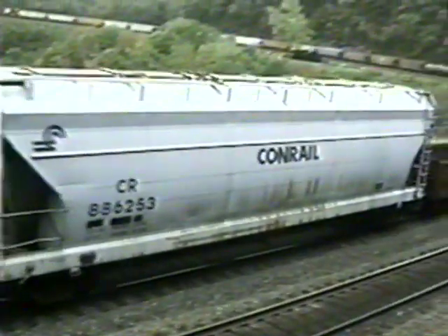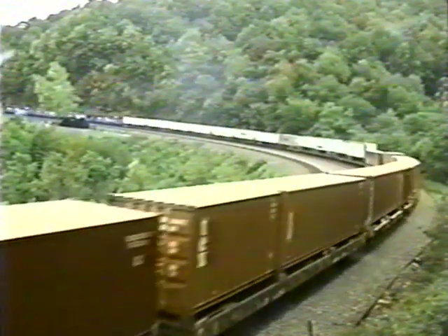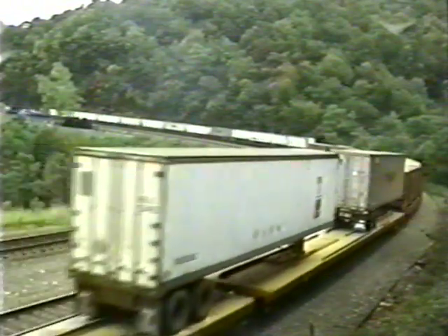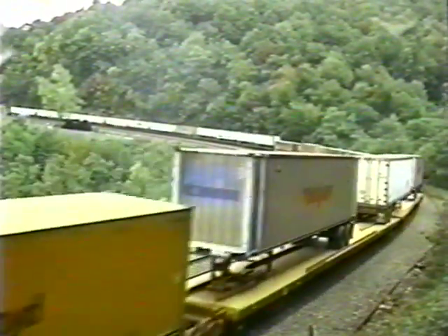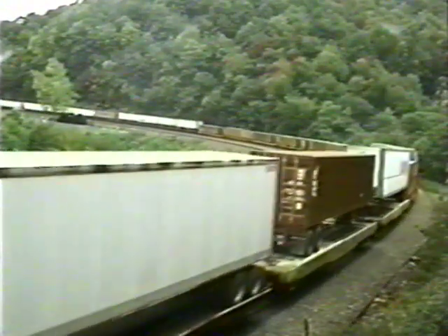Additionally, a run-in is a shock wave of force running through the train via the car bodies and couplers. It has two effects. It generates lateral forces due to the coupler angles, and it will tend to unload where the coupler height mismatch exceeds government and industry standards. Coupler angles are generally largest between long cars. However, a short car-long car combination has historically been shown to react to lateral forces generated by in-train forces.